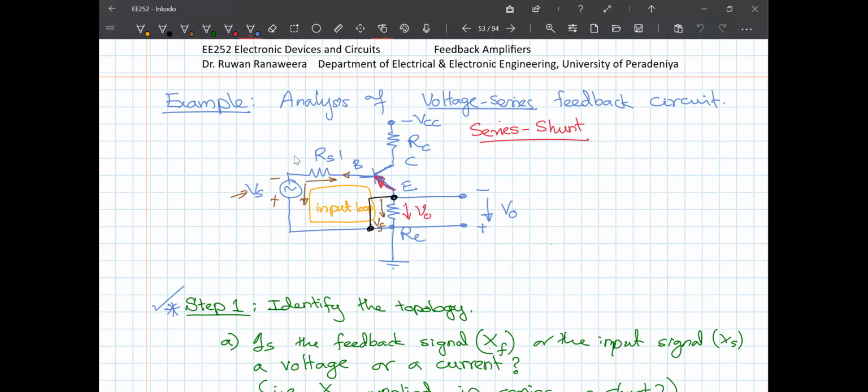What is the current? Simple, I has to be 0. So in order to do that, I need to open circuit this. Once I open circuit that, this IB will not flow through RE. However, at this point I am not assuming that IC will also go. Now in actual situation, if I remove IB, IC will also be reduced, but I'm not touching IC or IE, right?